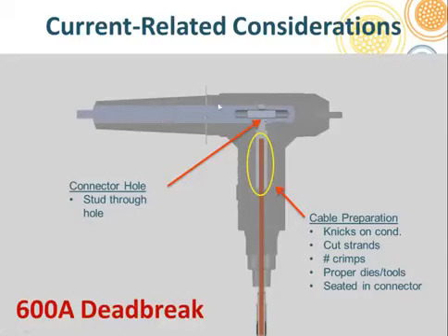Now he greases the 600 amp bushing, and now he starts to move the elbow housing over to put it onto the bushing. And it's just a little bit short. The cable's just a little bit short. So he lifts up on the elbow, figuring that he's lifting everything up. Unfortunately, what happens is the elbow slides off the cable adapter, and the hole only has to slide down 5/8 of an inch, and he puts the insulating plug through with the stud, and he misses the hole. What happens is he ends up pinching the top of the connector right here.